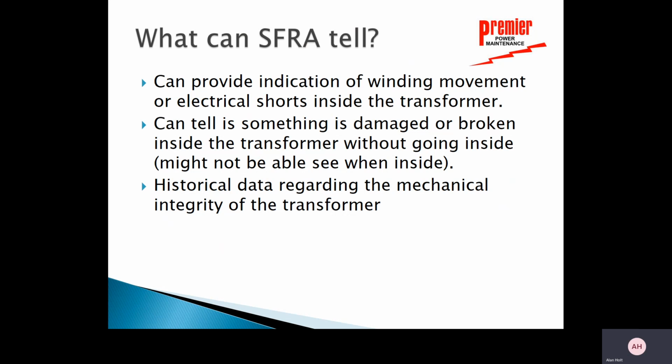But the other thing is, if you've ever been inside a transformer, you can't see much. So you might be able to do a thorough internal investigation of that transformer, and you still might not see anything wrong inside there, but this test will be able to tell you that there is something wrong. And with practice, you can actually get a good indication of what part of that transformer the problem's in. Now, the other thing that's really important is historical data is super, super important. I can't stress enough that historical data on the same transformer is the best thing that we can have to review for our test.